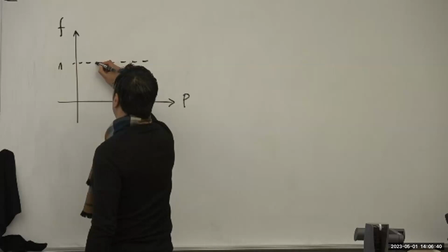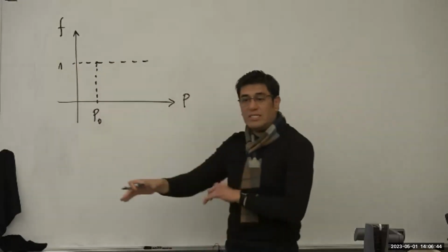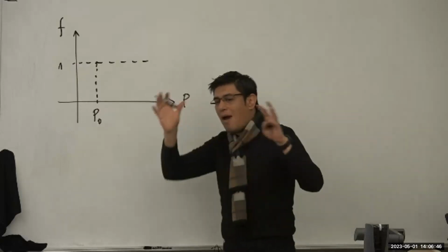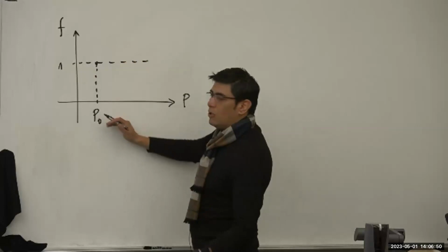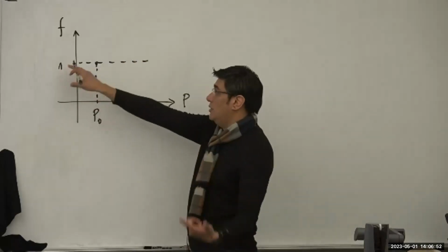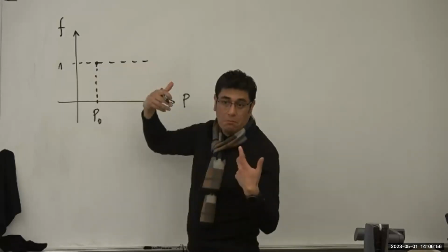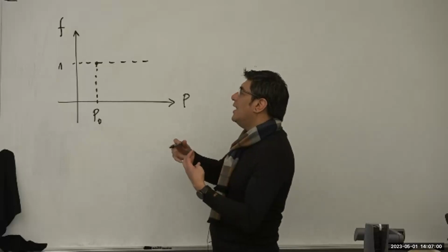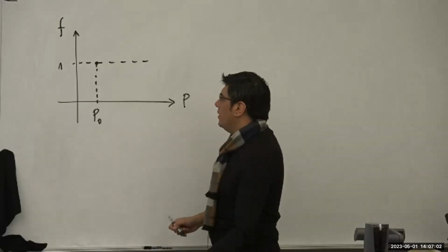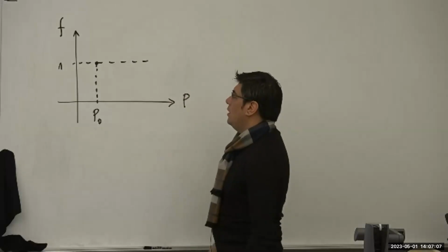And if this is 1, then you have an initial power, which is P0, that is the set point. We will run the power flow to initialize all the variables, assuming that the generator will produce P0. We will assume that the frequency is 1 per unit, and that is the initial equilibrium point. But if you have a disturbance that leads to a power imbalance, let's say you have more load than generation,